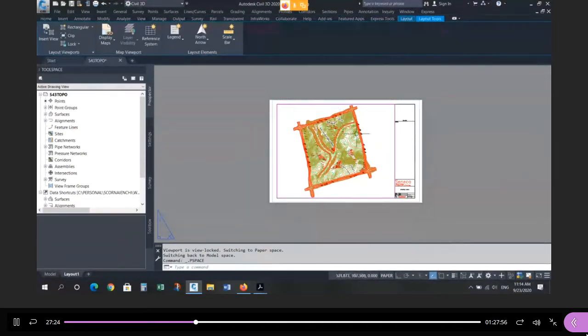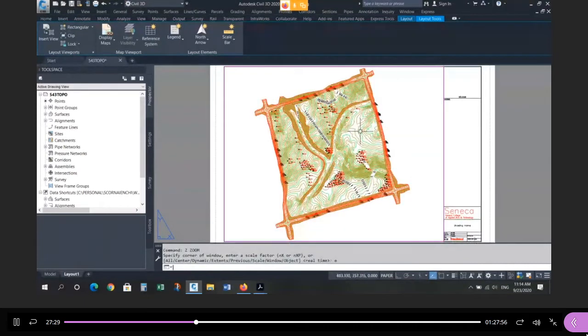And I'll be checking for that. Make sure your scale factor is correct. Okay? So that's how you create the viewport. That's how you get your scale. So for this particular drawing, you're going to use a zoom factor of 0.5 to establish a 2000. So you're going to print this at 1000, but everything in that viewport is half the size. The scale will actually represent 2000.